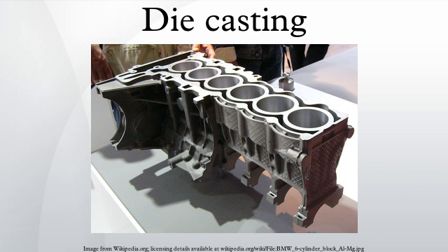The most common defects are misruns and cold shuts. These defects can be caused by cold dies, low metal temperature, dirty metal, lack of venting, or too much lubricant. Other possible defects are gas porosity, shrinkage porosity, hot tears, and flow marks. Flow marks are marks left on the surface of the casting due to poor gating, sharp corners, or excessive lubricant.